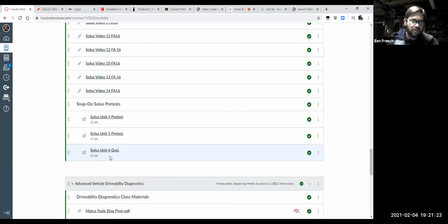you have an Autotech, or if you have a scan tool that can pull generic OBD2 data, that's all you need. I also don't want to nickel and dime you and tell you you have to have the 327. No, you don't. All I want you to do is be able to pull OBD2 generic scan data, because my job is to get you to where you can get the most diagnostic information from that OBD2 generic data. And if you have anything else available on top of that, whether it's the Snap-on or any manufacturer supported PIDs, that's going to be a bonus.